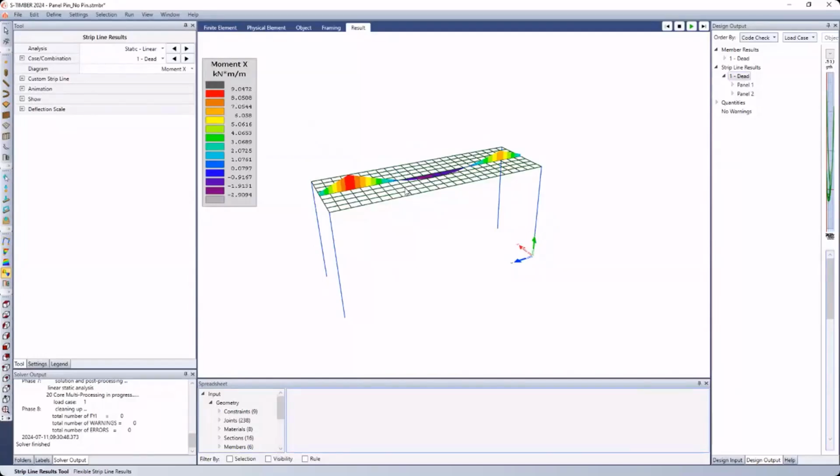And we're seeing here that the shorter cantilevered panel, this panel on the left here, is also seen to provide some sort of almost vertical support to the longer one, as we can see from this type of moment diagram. So it gives us the ability to study this behavior in a different light. These aren't behaving like concrete slabs that are one continuous, monolithic object. They are behaving as individual panels that are connected in the way we decide them to be.